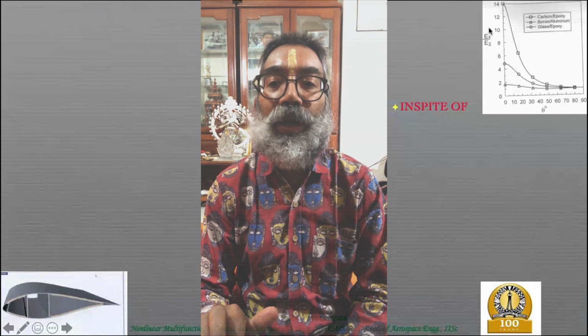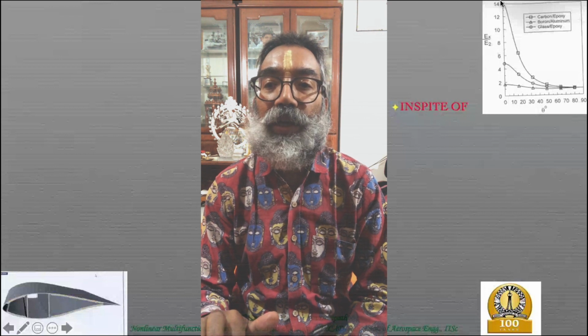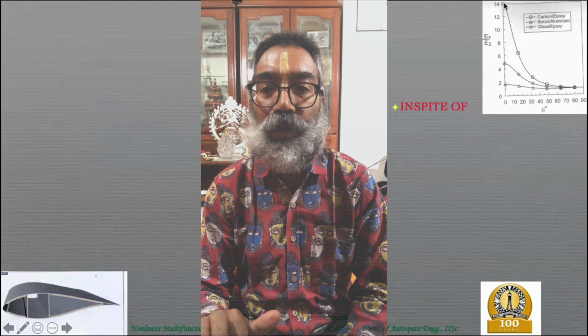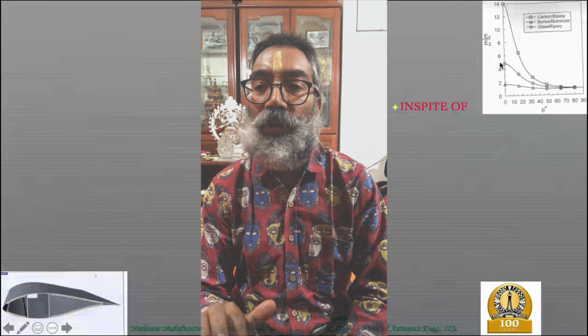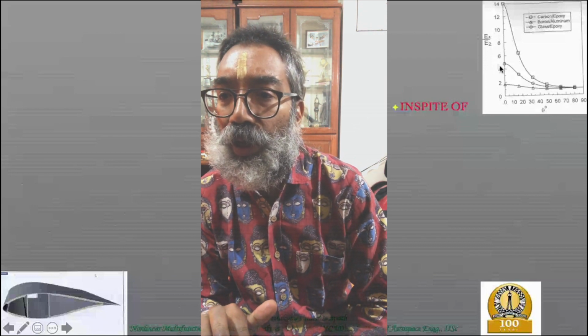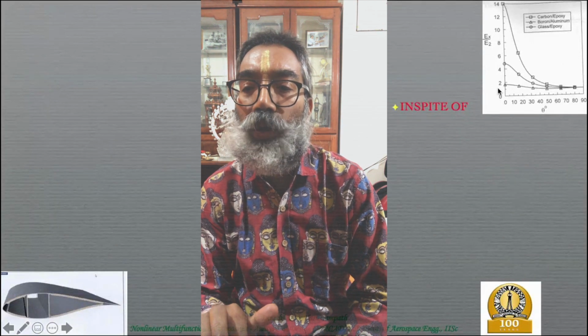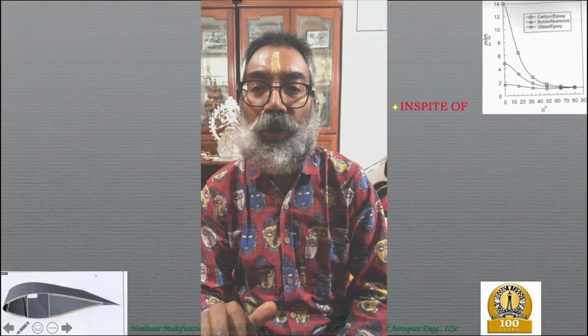Now, if you're looking at the Young's modulus along the fiber direction, that is fairly high. So it's 14 times, for example, for the carbon epoxy composite compared to the transverse Young's modulus. In the case of let's say glass epoxy, it's about 5 times, and in the case of boron aluminium, it's about close to 2 times the transverse modulus. That's the longitudinal modulus.